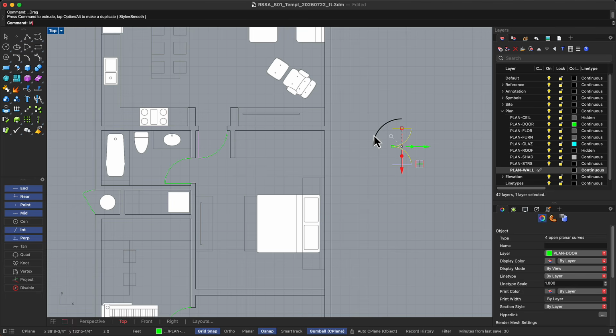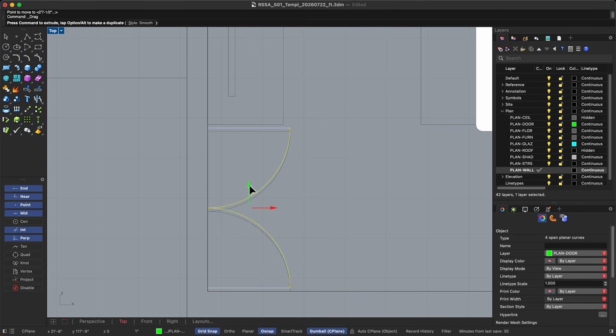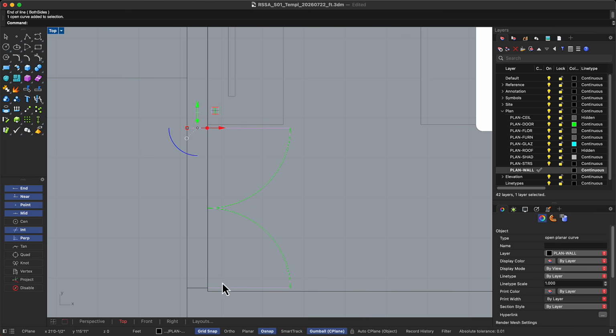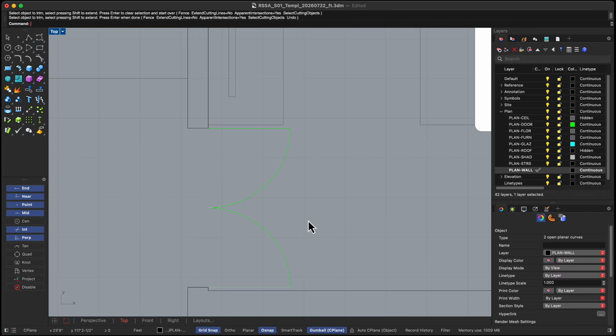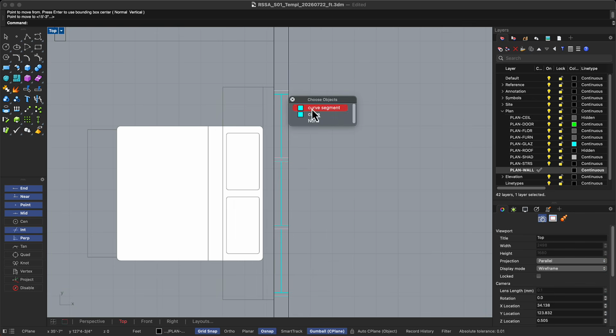Make sure that when placing private room doors, they protect views into the bedroom and bathroom, and every swing should clear fixtures, cabinets, and circulation. On planned glaze, place windows according to what each room needs. Use larger glazing to connect the living area to daylight views and the patio.